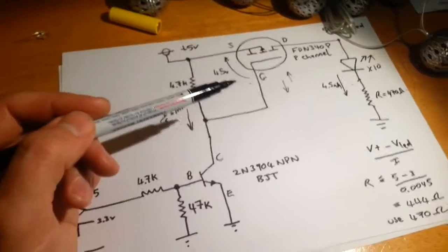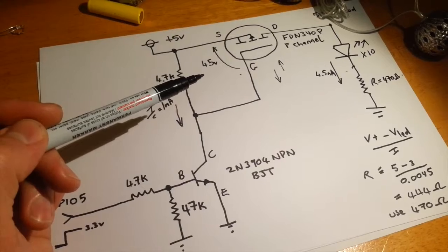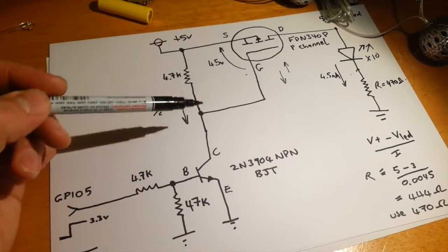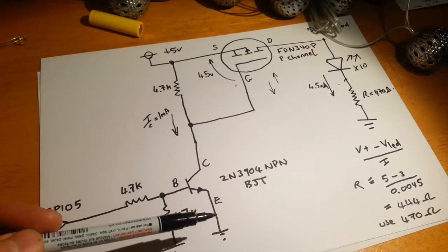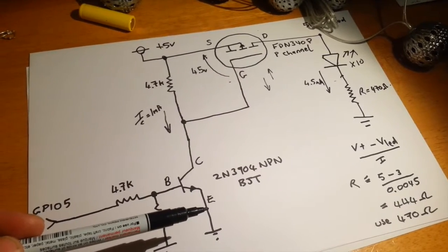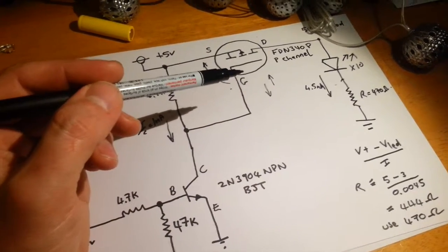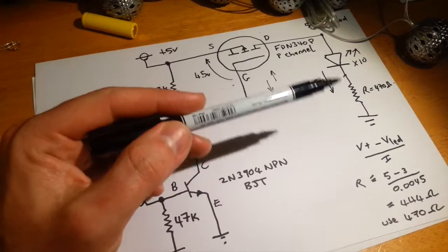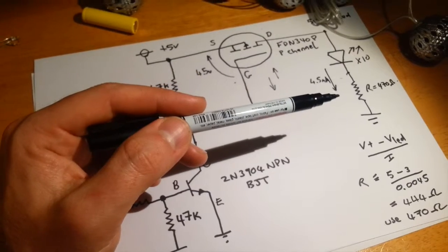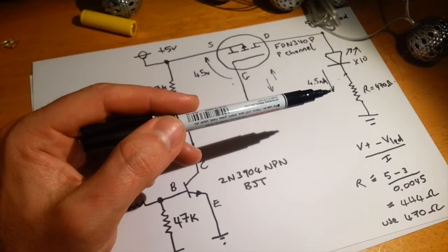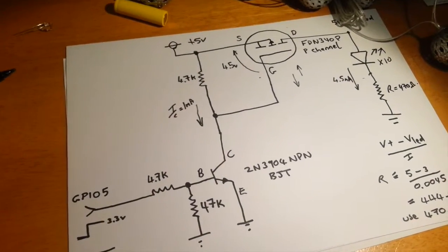The other thing is that this circuit is really overkill for the application that I'm using at the moment. So I could have potentially just inserted the LEDs here and had the NPN BJT here turning those LEDs on and off directly. But I wanted to give this circuit a bit of a try because I'd like to switch some things that require larger currents here. So some low voltage amplifiers, maybe bigger strings of LEDs and that sort of thing. So that was part of the consideration for designing it this way.